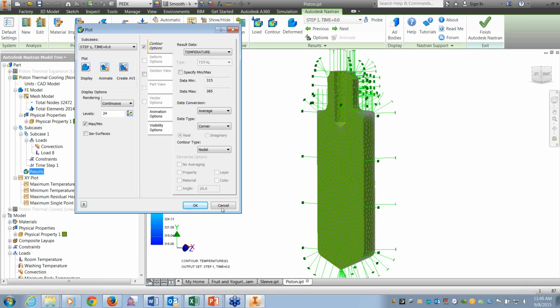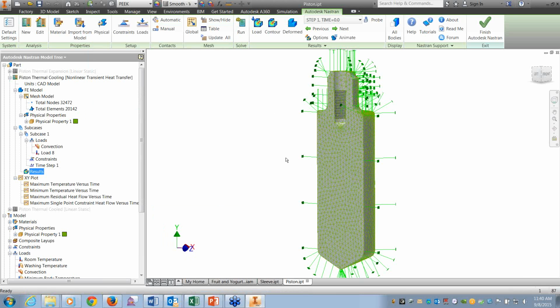So let me pause here for a moment and recap what I talked about today. I talked about how Nastran In-CAD brings more capability into the Inventor environment that we haven't had in the past. It directly reads my CAD geometry, and again, I'm saying Inventor. It is available for SolidWorks as well. It's bringing material properties over from the model. I can reassign to other properties here at this level if I wish. I can tweak those properties if I've got more information available here.